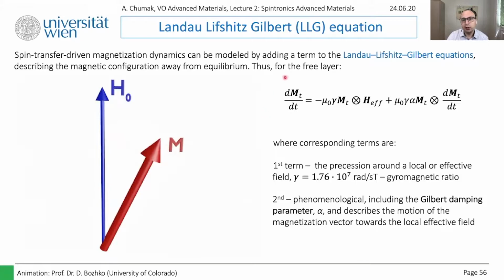But the Landau Lifshitz torque equation tells us that this is not what happens, because you see here a cross product, exactly like a mechanical spinning top when it's precessing. First you make your top rotate, it rotates vertically and it just stays, nothing happens. But at some moment when it's losing its kinetic energy, it starts to fall down. And in this moment, your mg force starts to act, and this mg force wants to simply put it down.